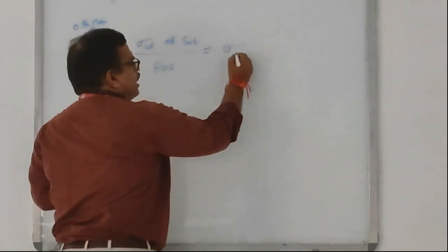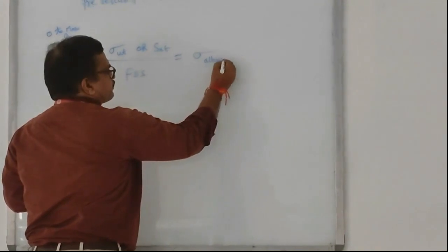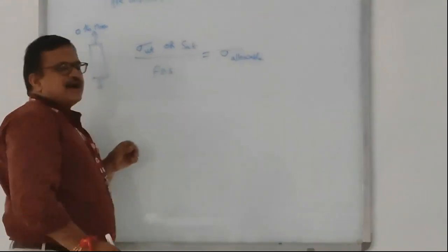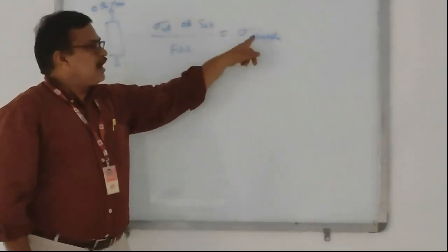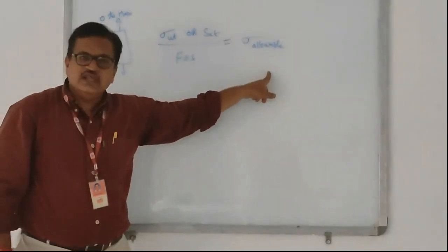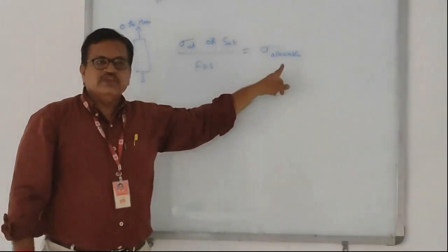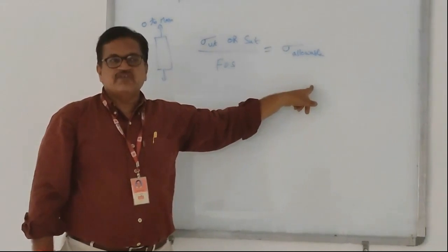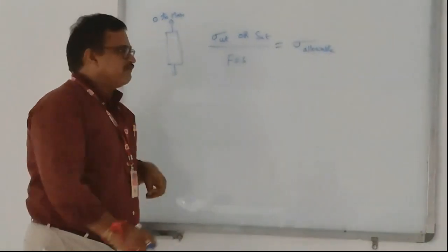This is known as allowable stress, or working stress. The allowable or working stress is generally used to determine the dimensions or safe load carrying capacity of the member.